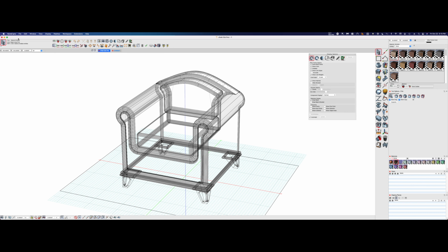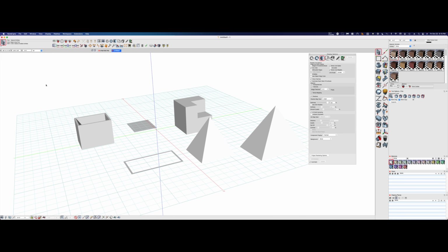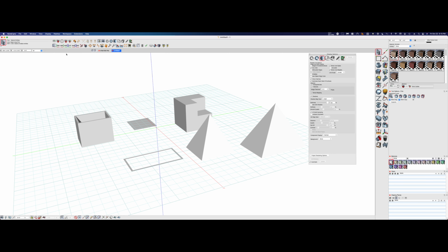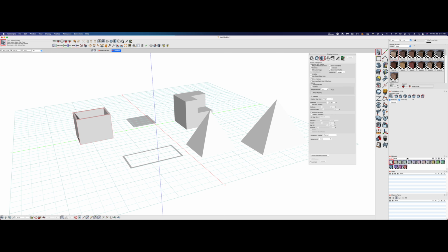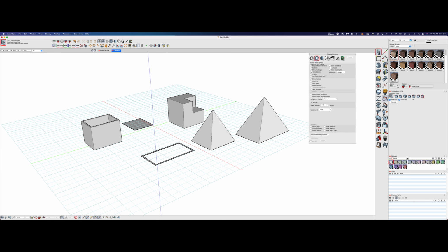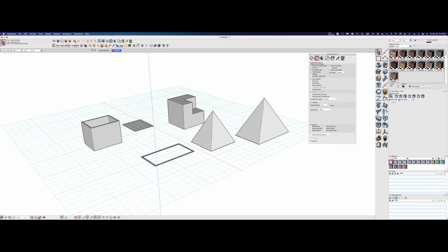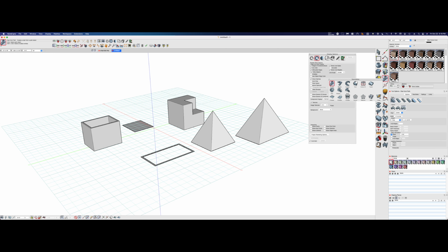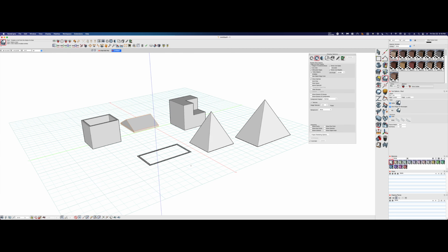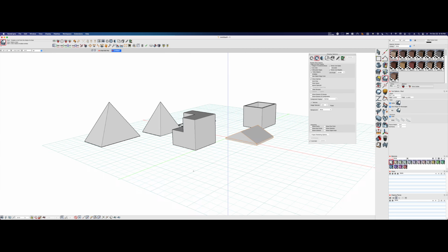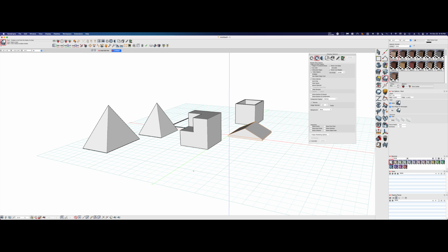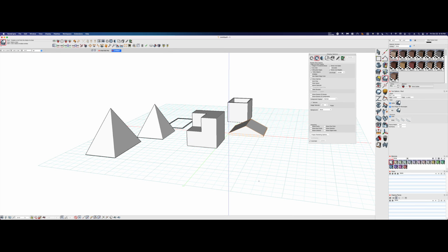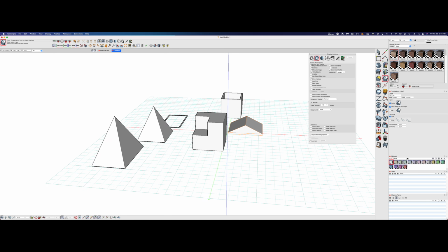Now, I did say it was a general purpose modeler, right? But it does have a little bit of automation. They don't get carried away with it. They have a roof tool. I'll show you how often I use that. I think it's underneath... no, that's just... oh, this roof tool. If I click on any flat, you see, I just created a roof on that. Now it is very basic. It's not detailed. I would have to go in there and detail it, but it can do it.